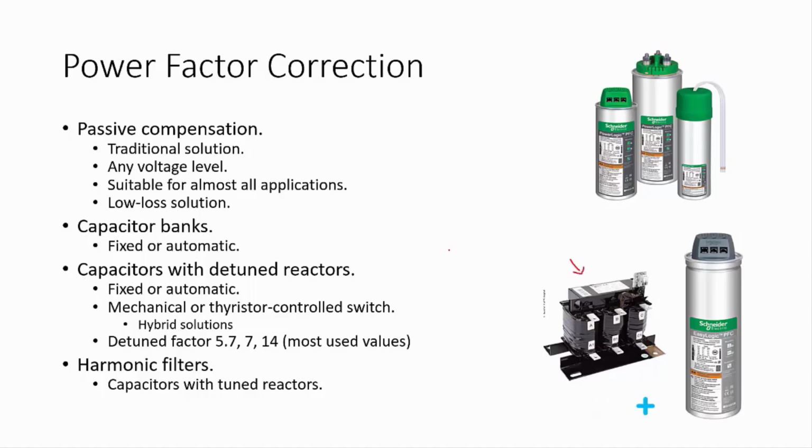Now, capacitors do not tend to respond well to high harmonic content because they can have internal overvoltage and internal overcurrent, which degrades the device and shortens the lifespan of capacitors, including many other electrical phenomena like overvoltage when connecting other capacitors, right? So a way to improve the performance of these capacitor banks is to add detune reactors, which control in a way the harmonic contents of the bank.